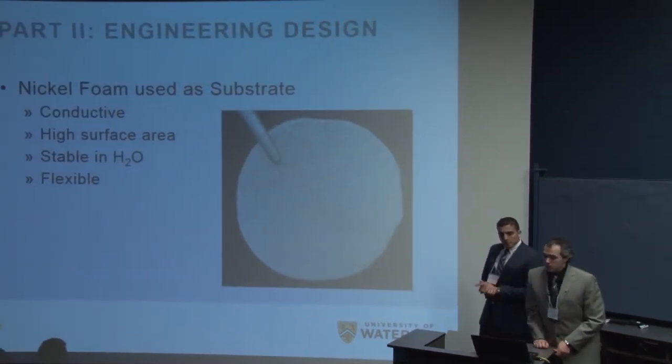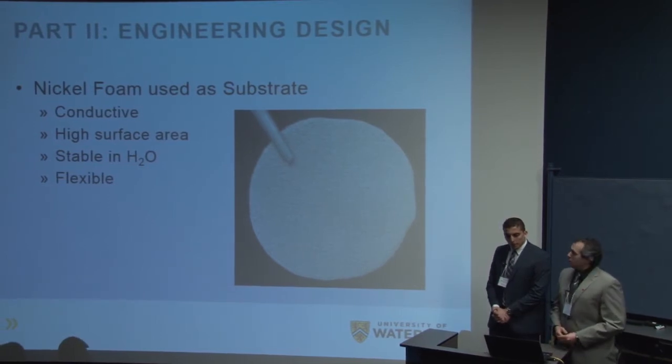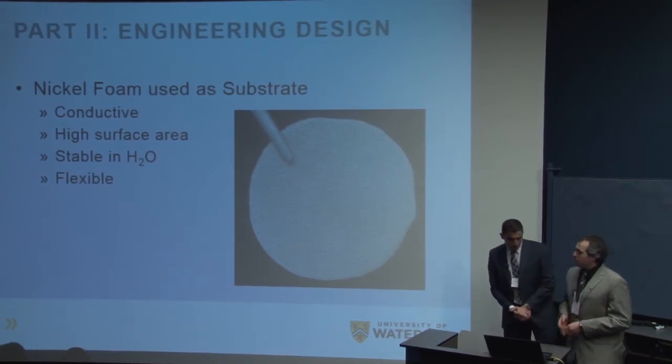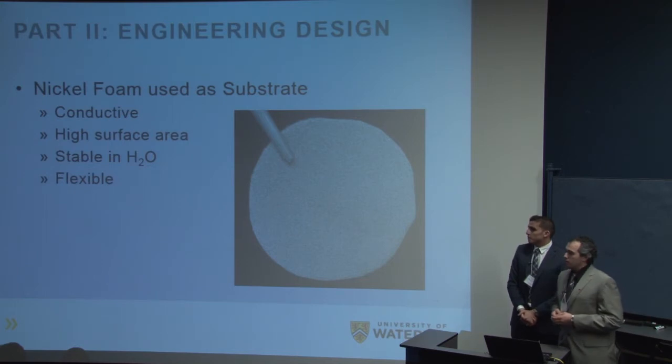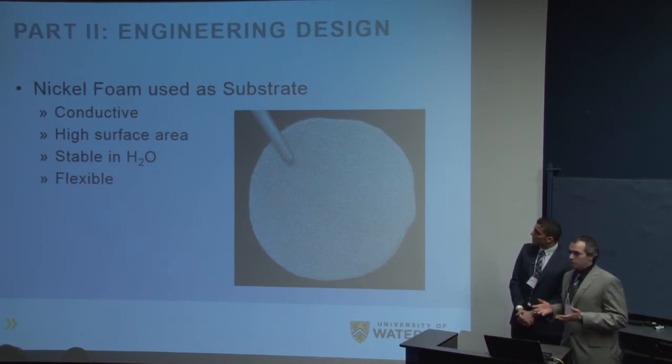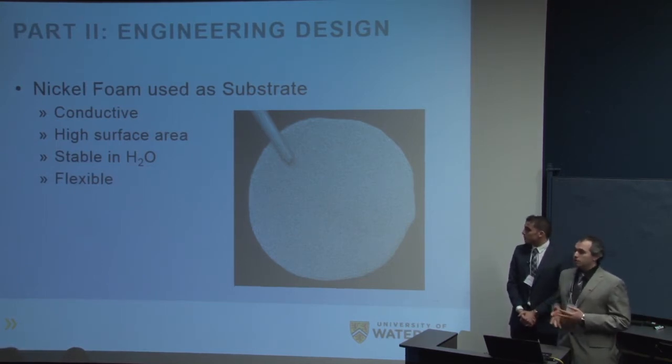For our engineering design, we decided to coat our material on a nickel foam. We decided on nickel foam because it's conductive, it has a high surface area, it's stable in water, and it's flexible, and also it's not very expensive.